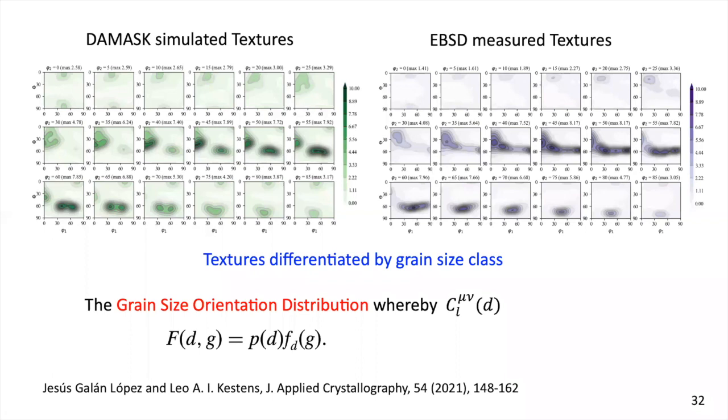As I told in the beginning, a texture is in fact only one element of the microstructure. And you should integrate the texture. The ODF, the orientation distribution function, is a statistical description of the crystallographic orientation of the microstructure. You can merge this with other microstructural elements, for example the grain size.